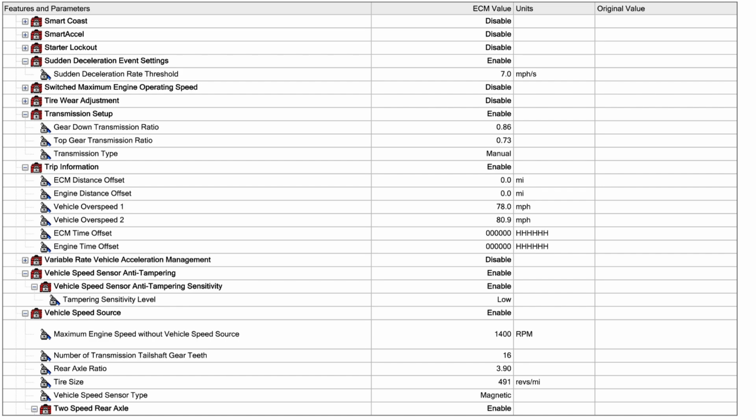Switched maximum engine operating speed. You can install a switch in the cab. If the driver flips it, the engine will only ever run that fast. A lot of times they use that when they're driving a pump off the transmission and say they're spraying in a field or they're running next to a hay baler and they want to run there for X amount of time. So they'll flip that switch on and just push the throttle down, and they don't have to worry about speeding up or slowing down because it stays right with the farm tractor that's pulling the baler. You get the idea.